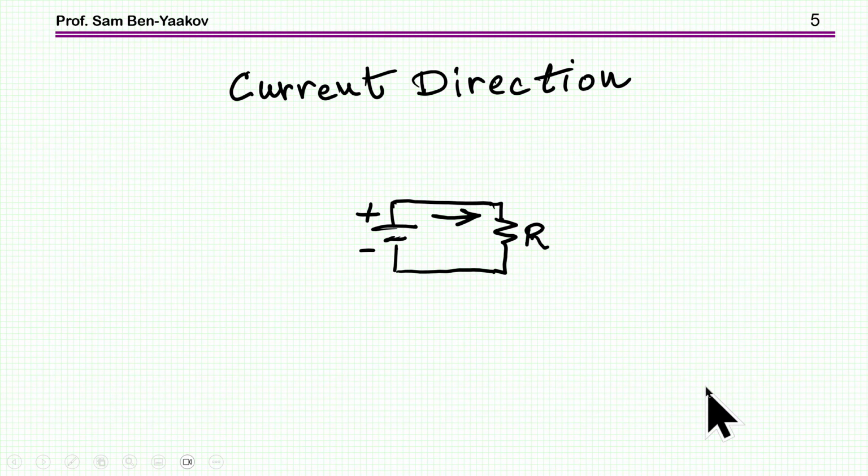And now what about the direction? There are many ways to look at it, and I'm actually looking for an intuitive explanation, not how the current is pulsating and how it's injected at the output, but something that is kind of basic. And the basic thing is that the current flows from a source to a load. That's it. So what I'm going to show is that you can describe each of these converters as an equivalent source and an equivalent load. And then the direction of the current is kind of obvious.